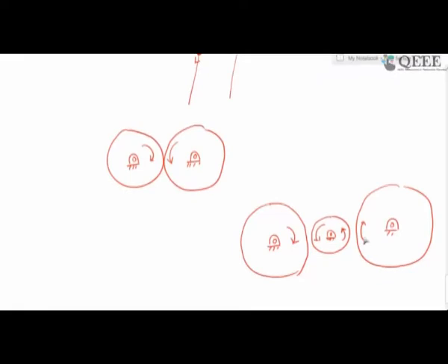The output will rotate clockwise when the idler gear is there in between the input and output. Whereas if the idler gear is not there, the input and output have reversed motion. Here this is clockwise, this is counterclockwise. Here the input remains clockwise, but the output now changes direction from counterclockwise, it becomes clockwise.